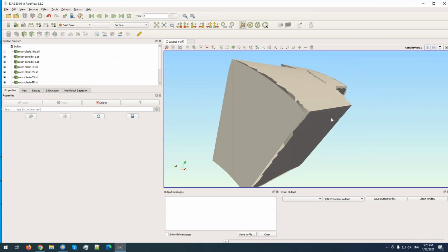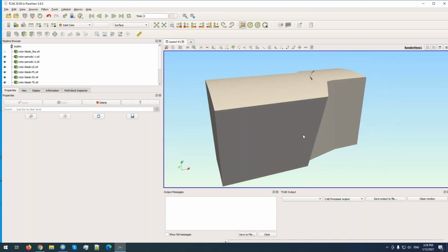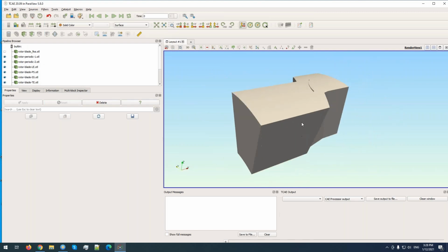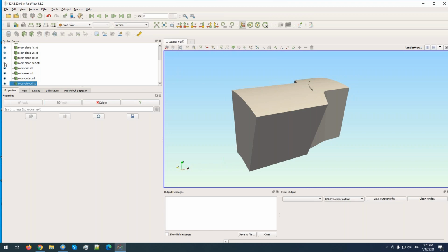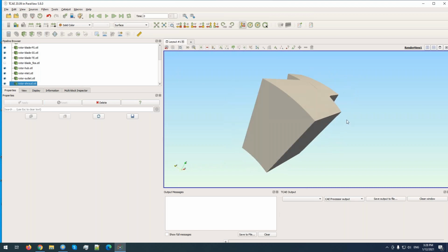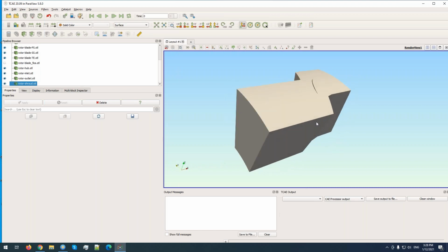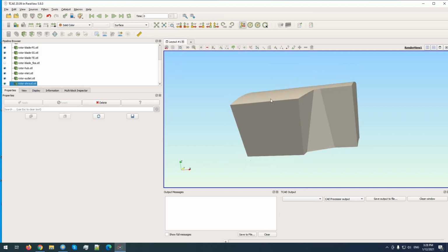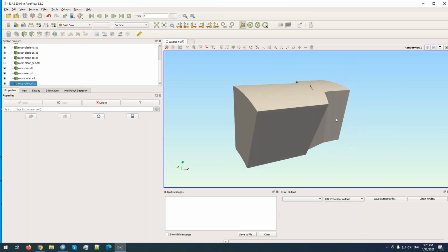So this is the typical geometry to simulate axial machines, an axial fan. We have only one segment to be simulated, as you can see, and it is closed in the periodical segment, including one blade only.